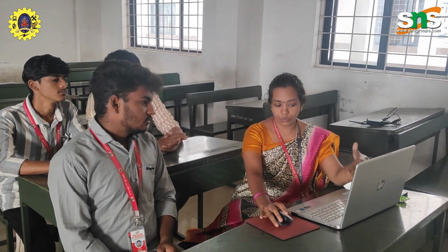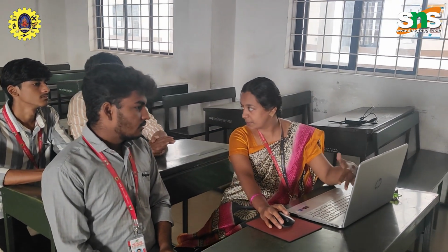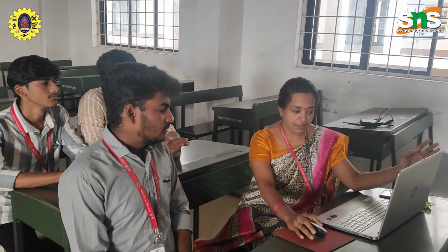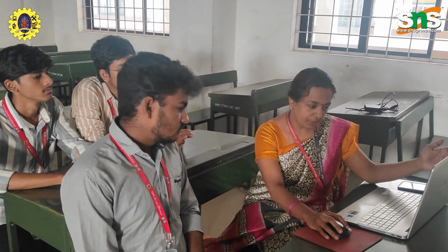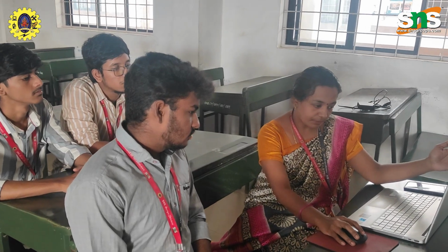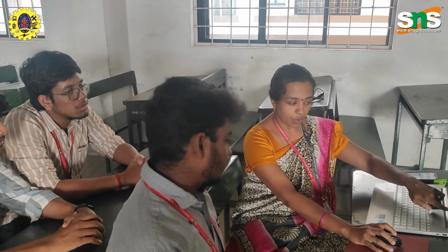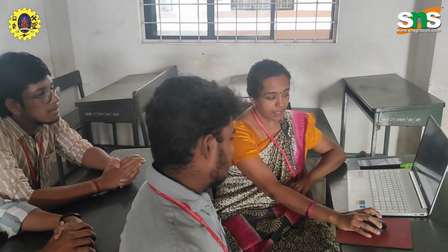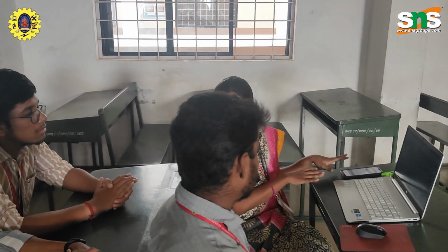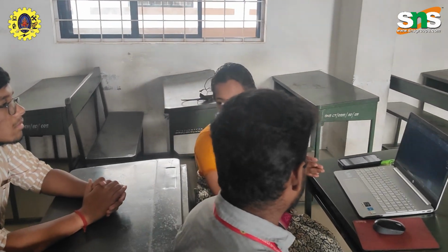If I want to convert this 2D workspace into 3D, I have an option here. So see here, this is nothing but the isoplane left, isoplane top and isoplane right. I am going to draw the isometric picture, or the 3D picture.